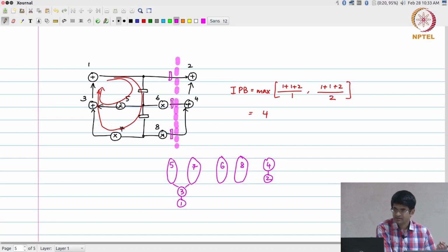This is actually very interesting, right. I have now got a potential implementation where, if I look only at the adders, I have achieved my target. So two things have been achieved over here. One is that the n that I want has now become equal to 4, and the number of adders has also become equal to 1, or can be made equal to 1 if I am able to keep the schedule like this, that is 4 and 2 over here and 3 and 1 over here. Since there are no dependencies, there is nothing preventing me from keeping it like this, right. So the maximum number of additions.